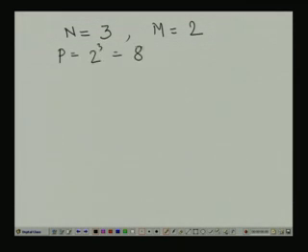If for n input variables I have 2 to the power n product terms, say here n equal to 3 and m equal to 2, so 2 to the power 3, p is 2 to the power 3 equal to 8. Now, if the design is such that it is possible to share the product terms, then instead of 8